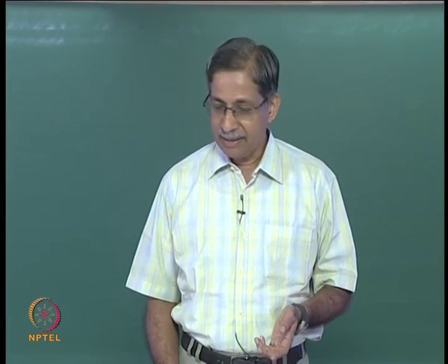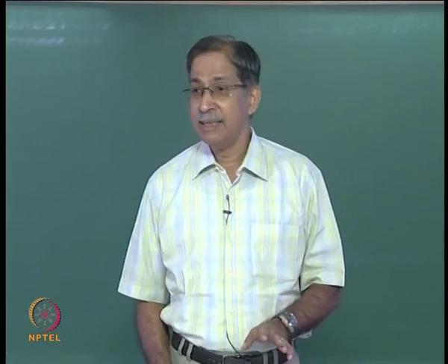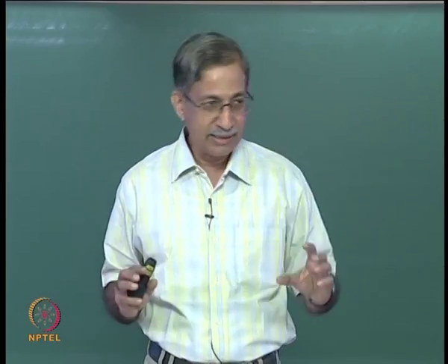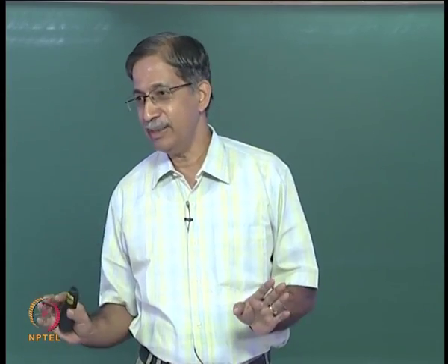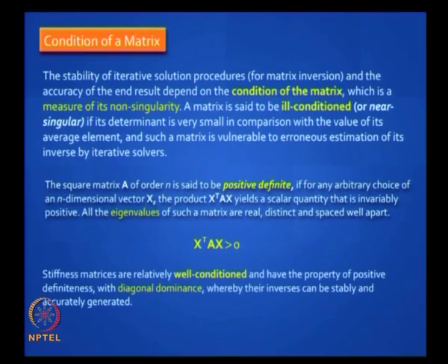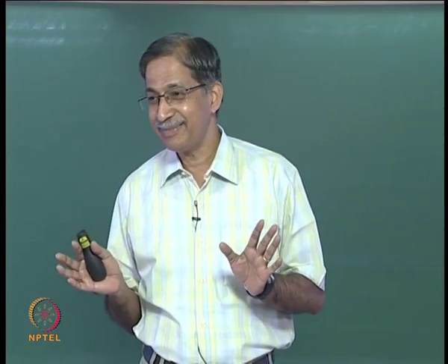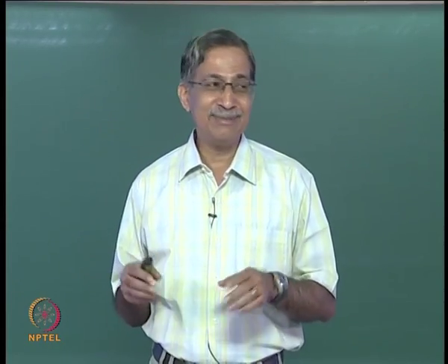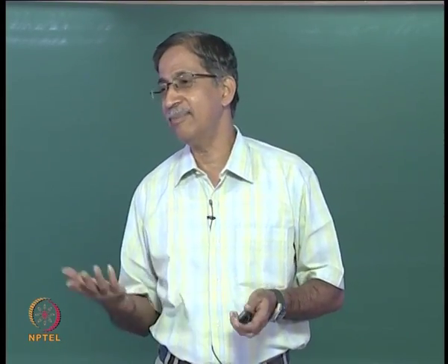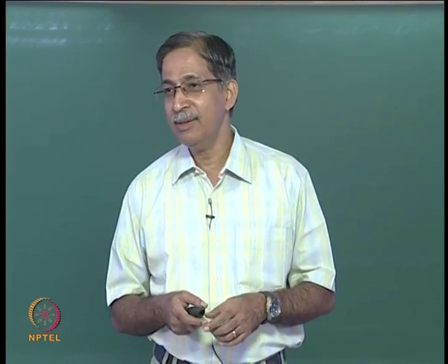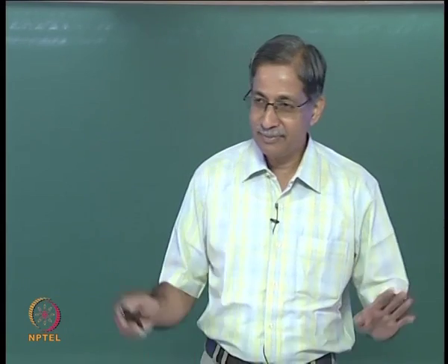Okay, and you can use eigenvalues to decide this. Basically, if your diagonal elements are heavy and they are positive, you got a well conditioned matrix. That is the thumb rule, and a stiffness matrix will be like that. Flexibility matrix, there is no guarantee. That is another reason why the flexibility matrix is not preferred, it is too flexible, you can run into problems of finding the inverse. Thank you, let's stop.